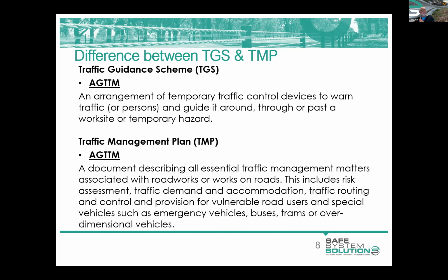And a traffic management plan is the document describing all essential traffic management matters. So it looks at the risk assessments. It looks at what mitigation has been put in place to address those hazards and risks associated with the roadworks and works on roads.